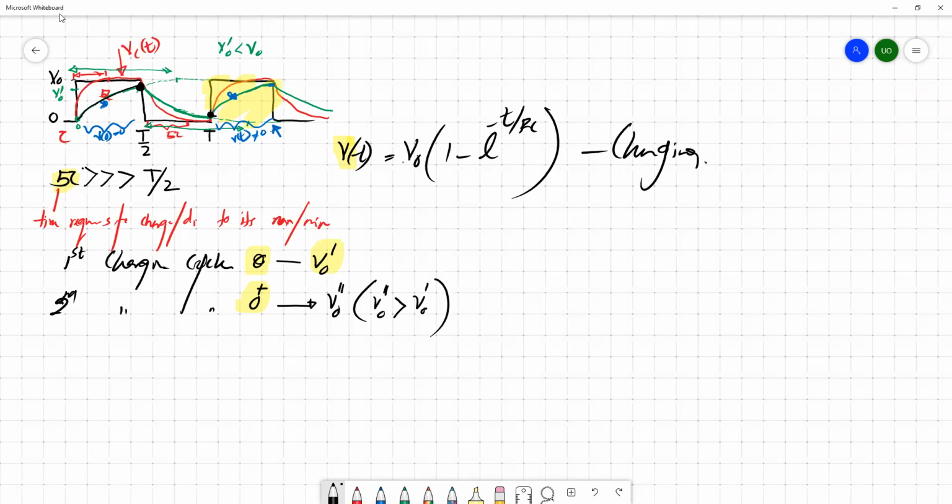If you keep R and C as they are, and the source voltage as it is, then the curvature of this profile remains the same. If it is linear, this gradient should be the same. So definitely if you start from 0, and here you start slightly above 0, then the ultimate voltage you reach here is slightly above. So that's the point I need to raise.